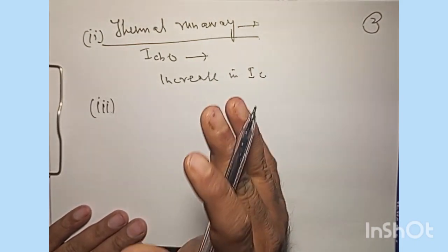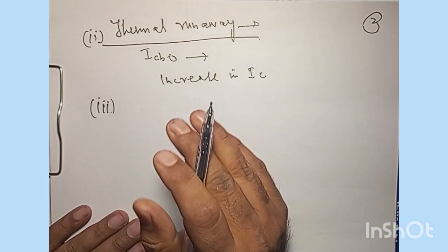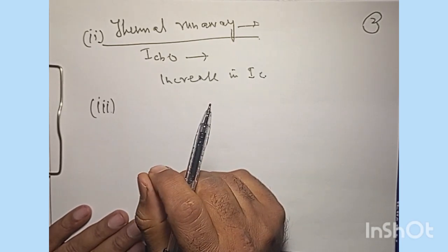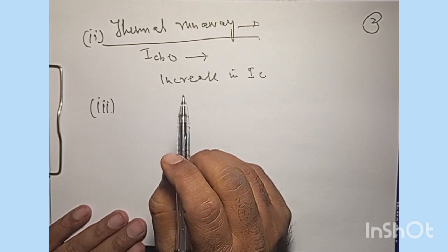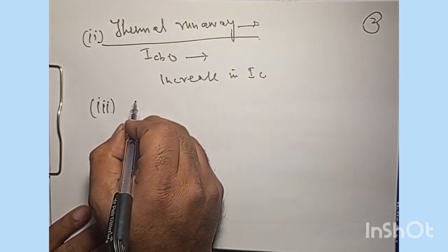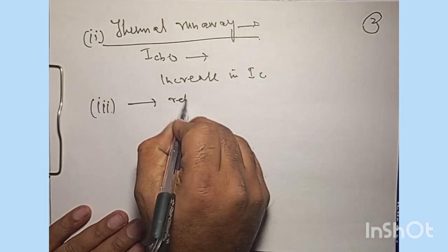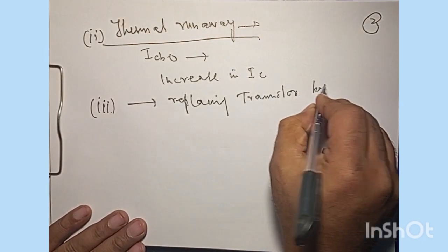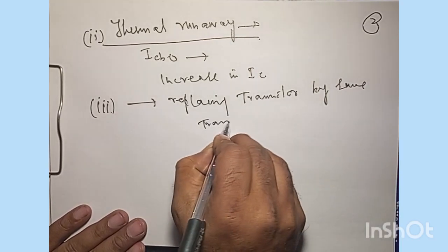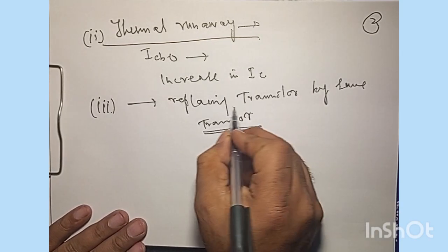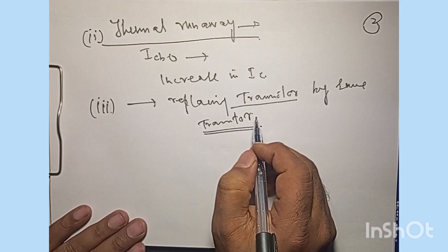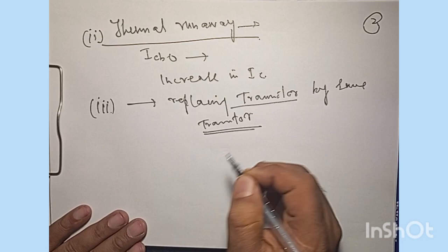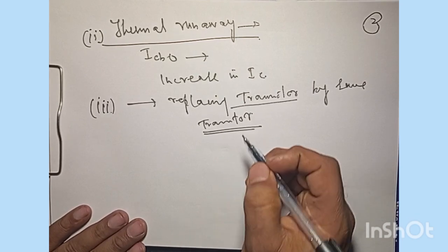When a transistor is replaced by another of the same type in the circuit, the variation in parameters changes the operating point, the Q point of the system. Even with the same model, the same number, the same semiconducting material, replacing a transistor by the same transistor does not mean the next one will behave in a similar way as the previous one, even though they are designed at the same time and grown under a similar environment. No, they will have differences in their actions.